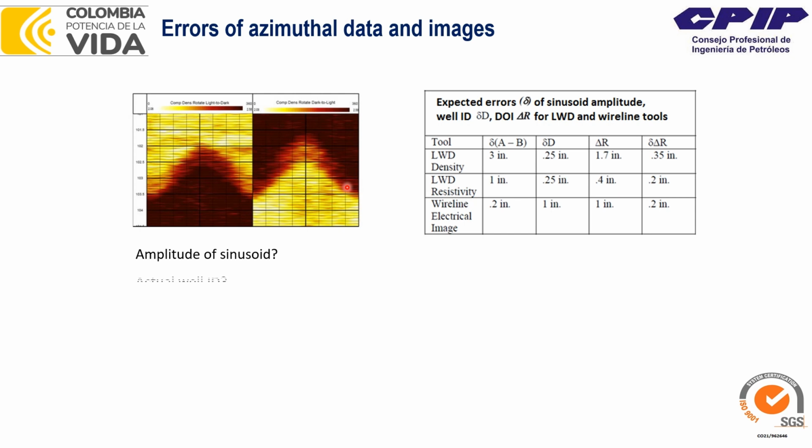Second parameter is the actual well diameter, okay. So if we have a bit size, normally we put in the formula the bit size like 6 inch or 8.5 inch and so on. But is it actually exactly 8.5? Of course in real life it is not.